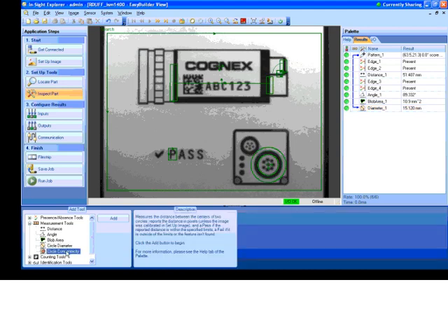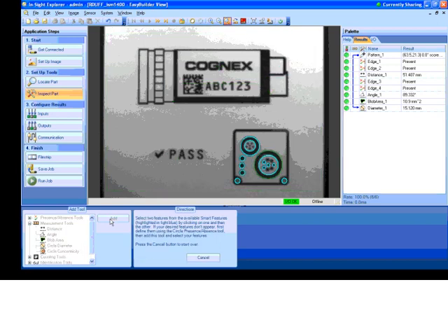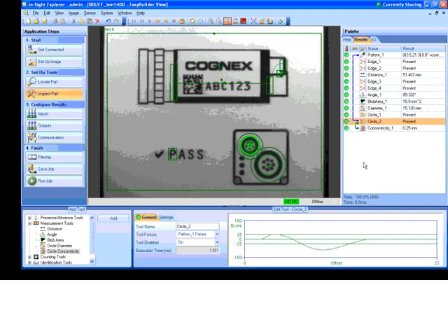And then the last of the measurement tools, circle concentricity. And this is the measure of the center of two circles. So I'll say Add. In this case, we're going to have to click on two different circles. So we'll measure from this one to this one. If I can hit it. There it goes. And it measured the difference between the two centers as 0.25 millimeters. And that is all of the measurement tools.